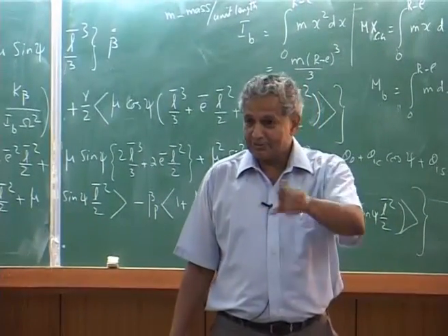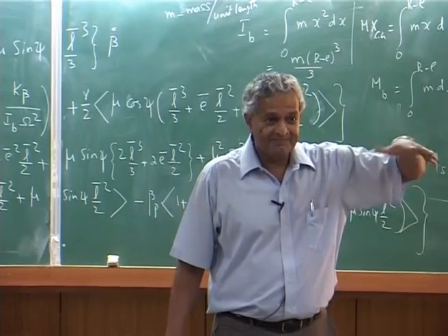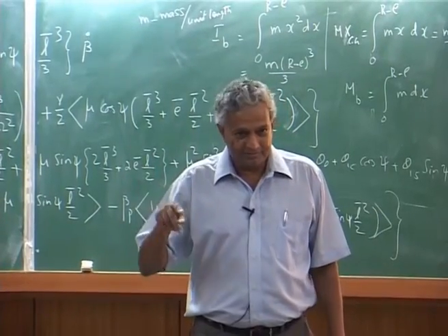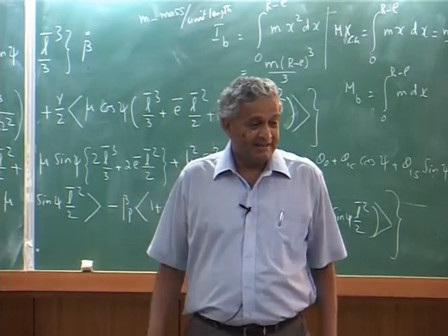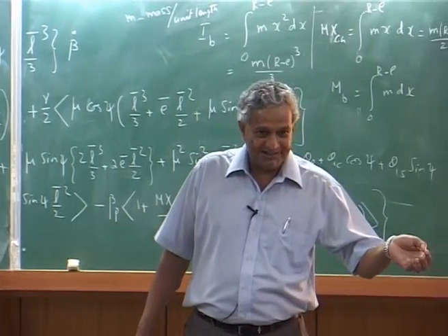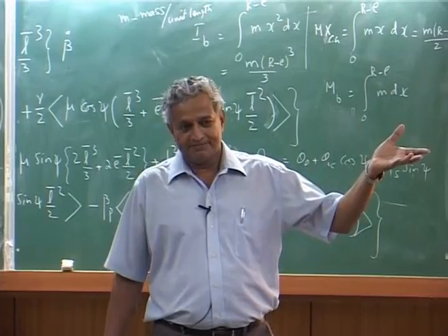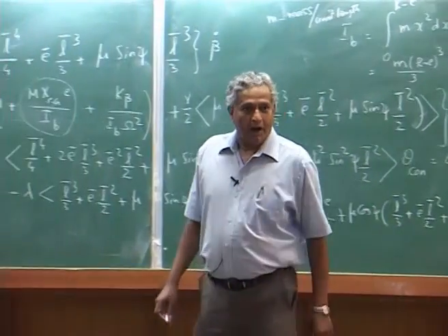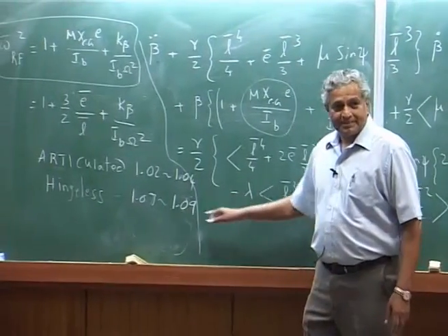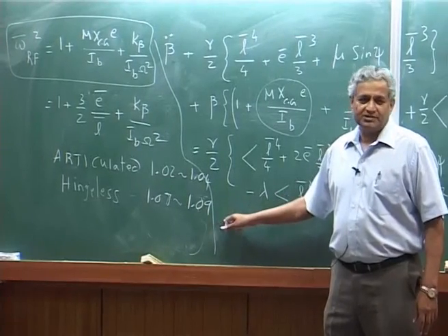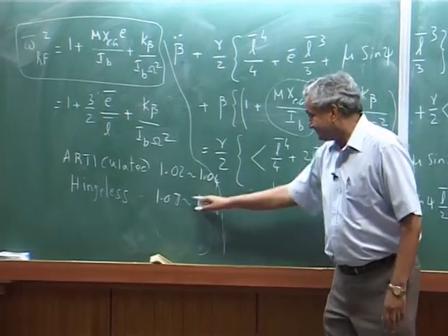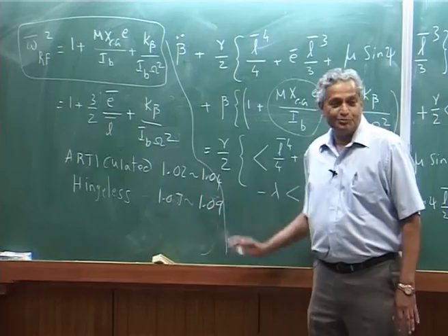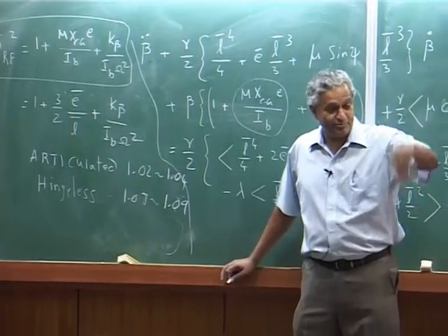More flap frequency, you remember earlier I said hub moments, you will have a higher hub moment, omega bar Rf square minus 1 over gamma by 8, remember. That means, if you have a higher flap frequency, you will get a higher hub moments. That means, pilot can generate more. Now, this is where how much higher you can go, can you go further, then they will say it becomes too sensitive. So, they try to keep it only maximum in this range, do not go too high, otherwise higher flap frequency, your higher moment, higher vibration.